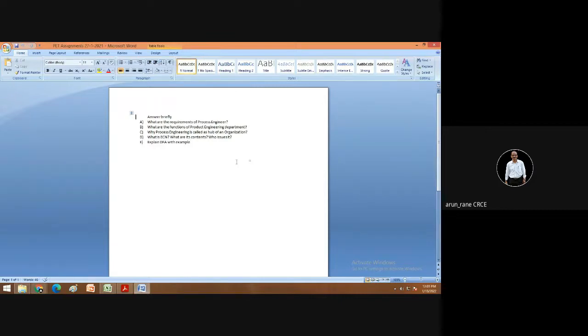Points, meaning assembly should be in one direction, in one position only. You have to use snug fit parts. It should be standard components, more or less the same. Like M10, then M8 and M10; it should not be M4, M6, M8, M10, M16, so many nuts and bolts of various sizes.